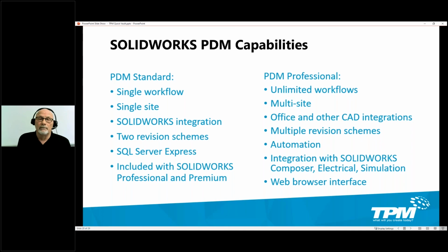It includes some automation above the PDF generation for SOLIDWORKS drawings. So if you need DXF output of flat patterns, if you need to generate STEP files in order to send those out for 3D printing, that's all available in PDM Professional. It integrates with the SOLIDWORKS desktop solutions like Composer, Electrical, and Simulation.